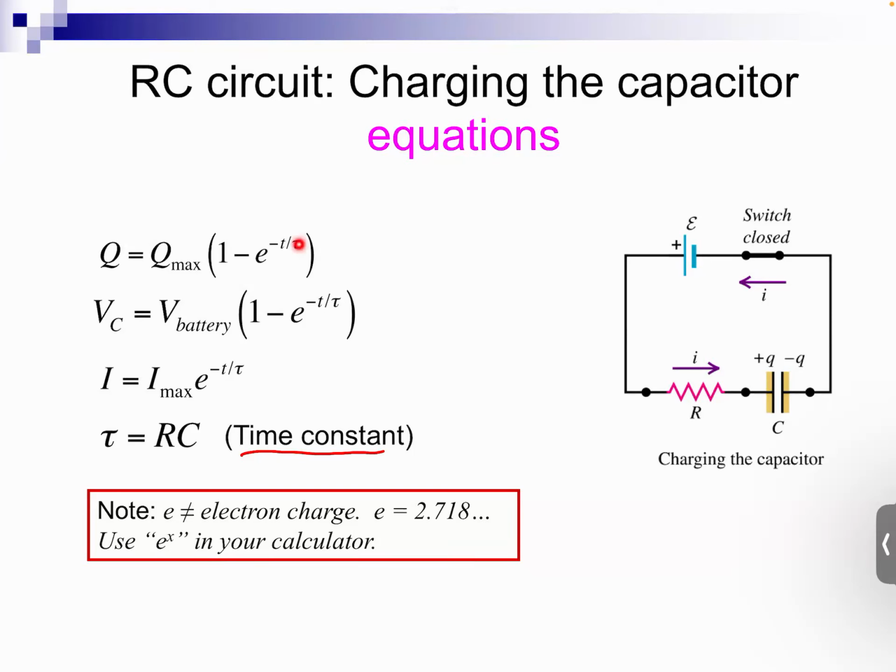So in this equation here, t is time, any arbitrary time for when you want to determine the charge, the voltage, and the current. So that's the small t there. Tau, of course, you have there tau. It's the same tau here. It's called the time constant. It's the value of the resistance times the value of the capacitance.